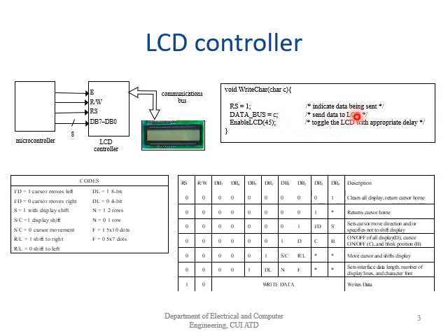So send data on LCD, and every time we write, read, or set the control word, we need to toggle the enable pin. Every time data is sent, whether control word or data, the enable bit must be toggled.